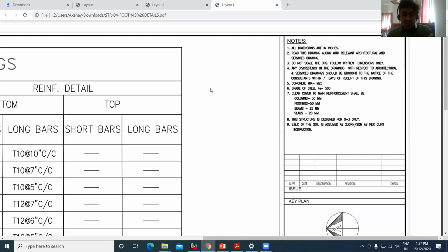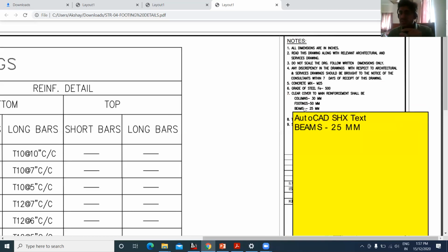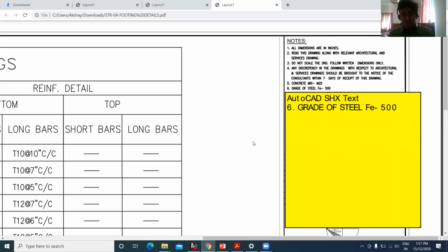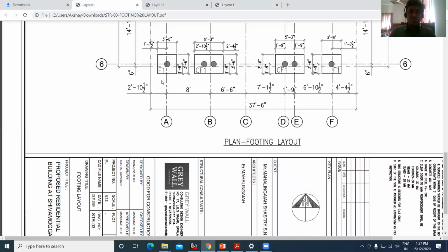So in that case, whatever drawing this structure consultant has given, we cannot use, because this drawing is specifically meant for a G+3 building. Just because you developed the idea of constructing one more floor over that, that doesn't mean that we can use this particular drawing. Again, we have to approach the structure consultant, and for G+4 we have to get the design done, because this design what you can see here, and yeah, I'll try to show you.